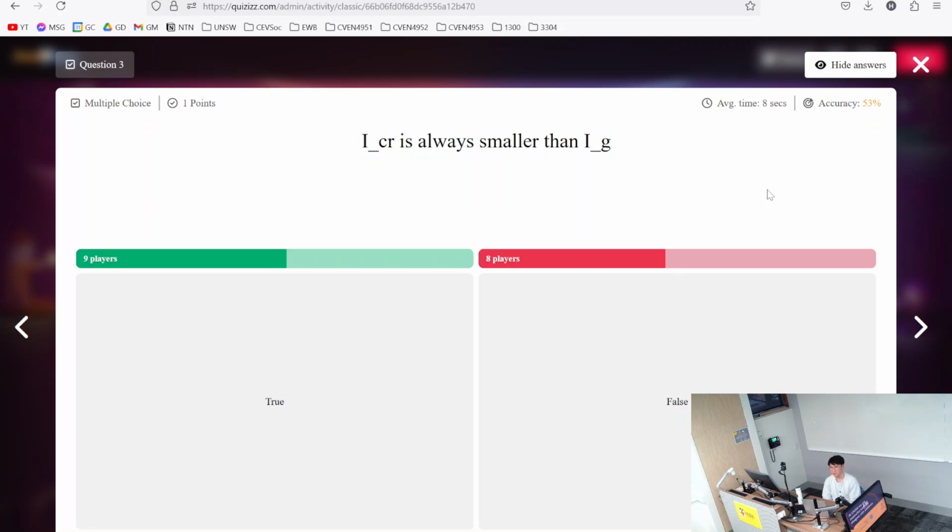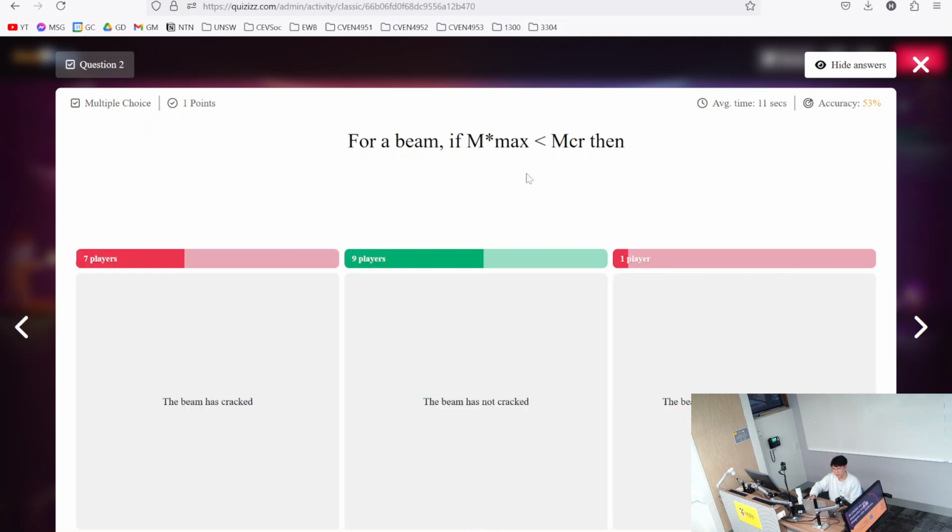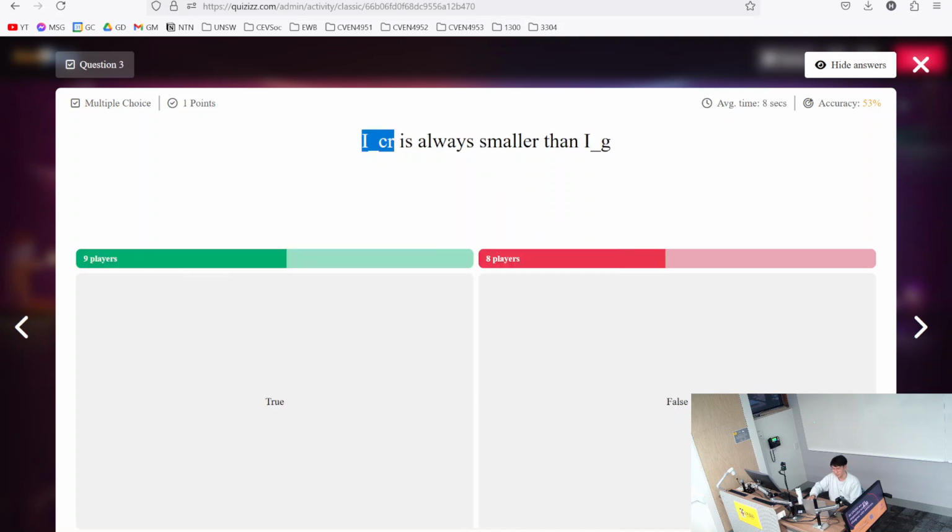Once the moment is greater than the cracking moment, your beam is cracked. And as you can imagine, a lot of that concrete area becomes useless, right? Everything under the neutral axis becomes useless, and so I_cracked is smaller than I_g.